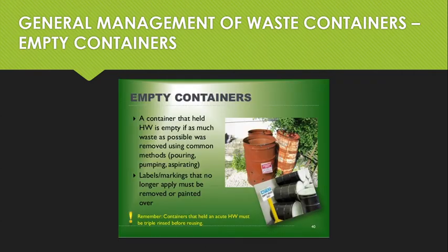Empty containers. Basically it just says that labels and markings no longer apply, need to be removed or painted over. In the case of listed hazardous wastes, we discussed that earlier and how I said anything they touch becomes listed hazardous waste. Well, that applies to the empty drums as well. So even if we go to pick up drums from a customer and they used to hold listed hazardous waste, well, I'll ask you, has that drum been triple rinsed? And if you say no, or the customer says no, then now that's hazardous waste. Maybe an empty drum, but it's hazardous.